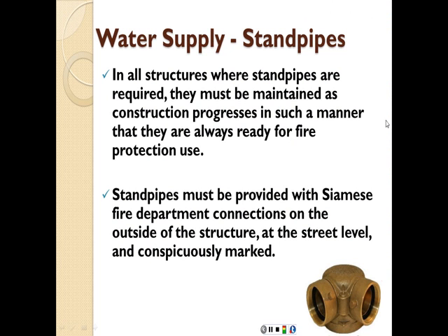Water supply standpipes. In all structures where standpipes are required, they must be maintained as construction progresses in such a manner that they are always ready for fire protection use. So these are going to be dedicated for fire protection. Standpipes must be provided with a Siamese fire department connection on the outside of the structure at the street level